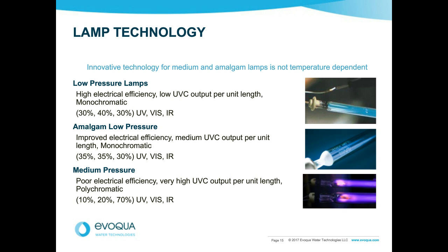Well, if we add chlorine to wastewater, we risk elevating a compound called a trihalomethane, which is a byproduct of chlorination, which is implicitly a carcinogen. It can do damage and harm. If we then try and discharge chlorinated wastewater, we have to remove the chlorine. Otherwise, we can have a devastating effect on the natural flora and fauna in the lakes and the rivers. So UV has long been very successfully applied to wastewaters.